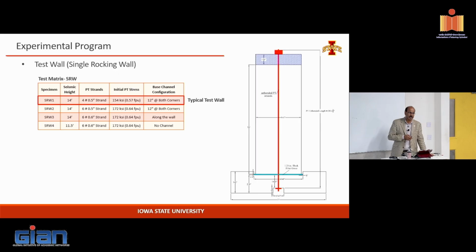One of the things they said was, we don't like the angle at the bottom. Their concern was 2. One is anytime you add something, it increases cost for us, so eliminate it. That's one thing. The second thing, which should be a concern for you also, corrosion. If the wall is on the exterior of the structure, the corrosion becomes a nightmare, and then you have to deal with that corrosion problem.